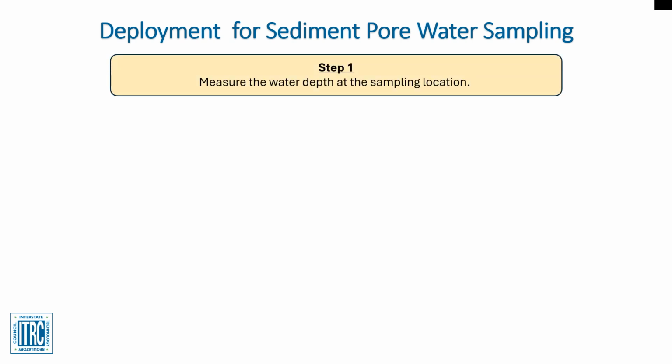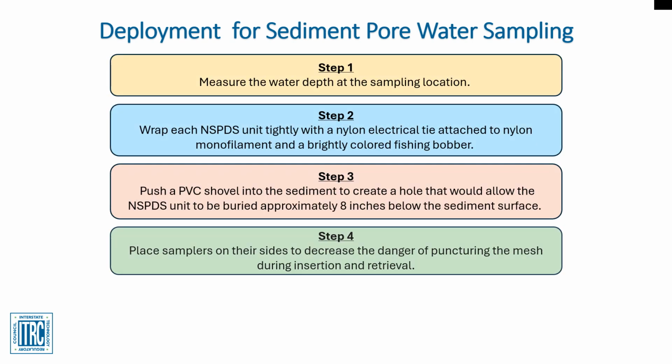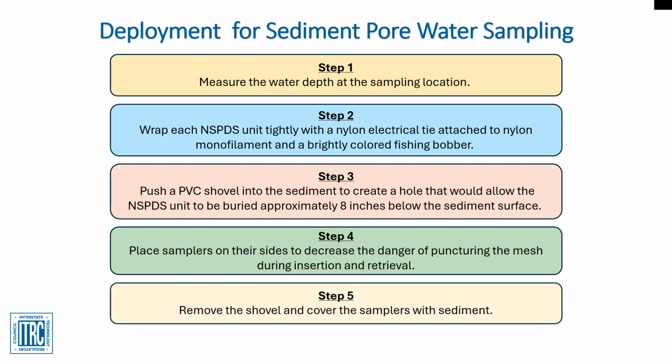When deploying the sampler into sediment, use the following procedures. Measure the water depth, if applicable, to properly document site conditions, and to determine the approximate depth from water surface that the device will be positioned.